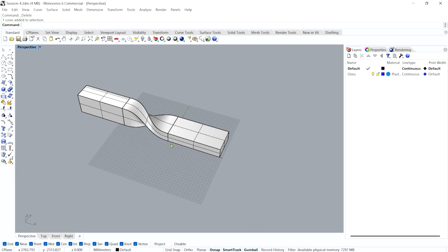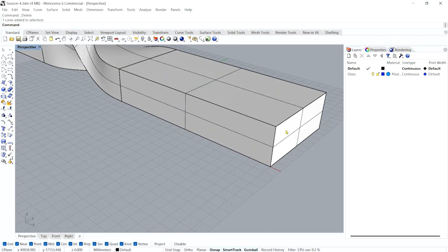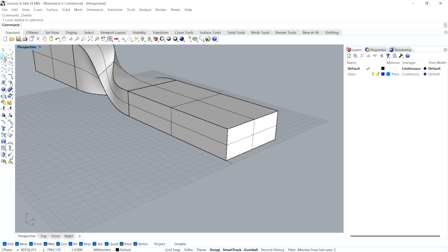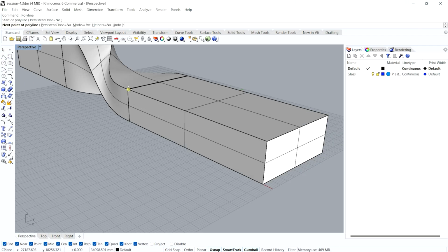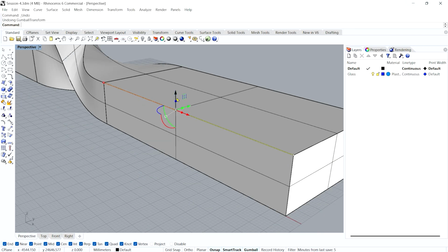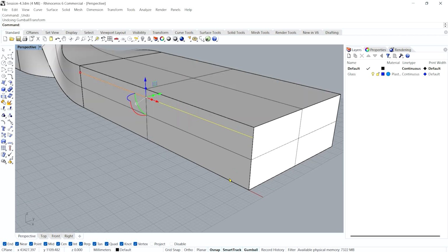Now next, what I will do, I will make the roof here and the slab, the floor, and this side and this side. So again, I will take the polyline command and will make a line here, and I will select this curve and use the gumball to bring this line again minus, let's say 1000 or 1500. Let's keep it the same. And same way, I will make another polyline at the bottom, or you can mirror this also. How to mirror this?